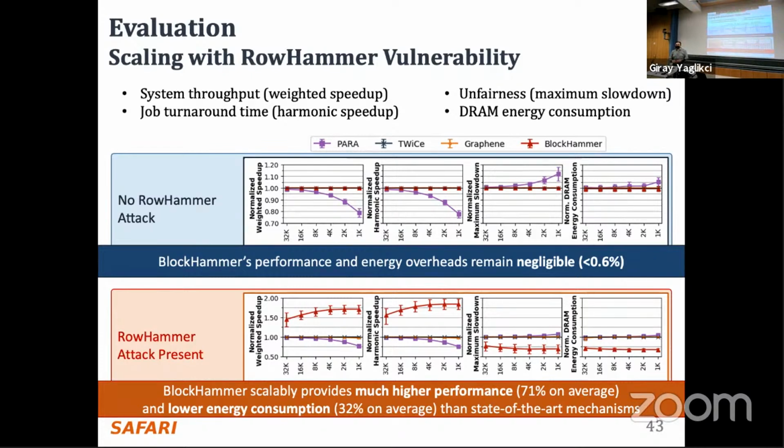Maybe you remember that from works like CROW, or ChargeCache. There's a behavior called row buffer temporal locality, row-level temporal locality, and over there it's some observed trend that when an application activates a row, there's a high chance that it's going to activate the same row again in the near future, and you can actually consider that as hammering, right?